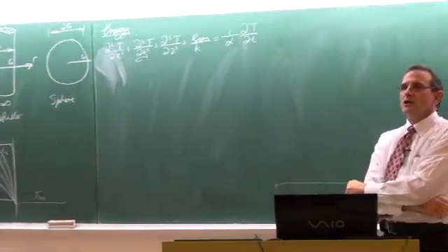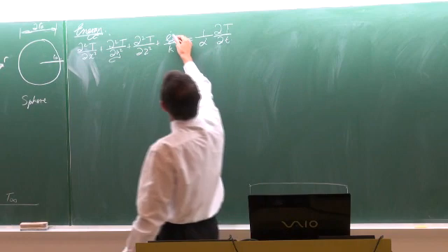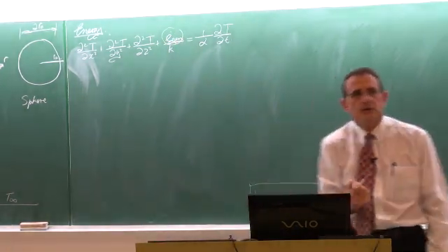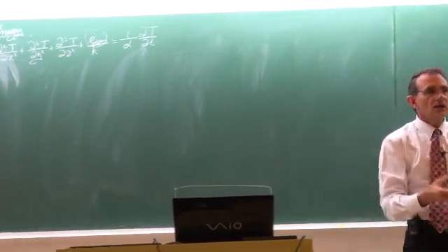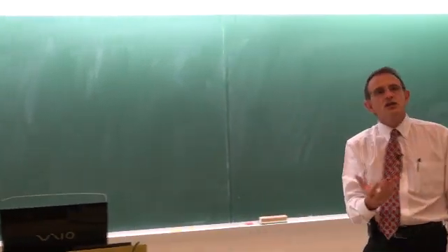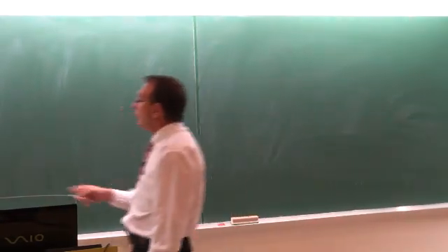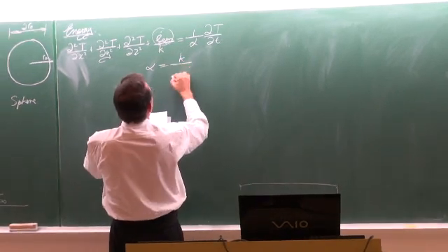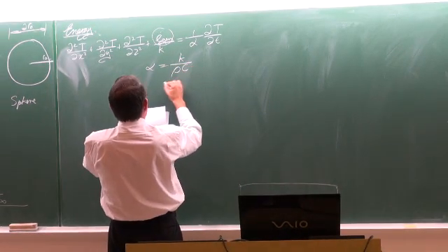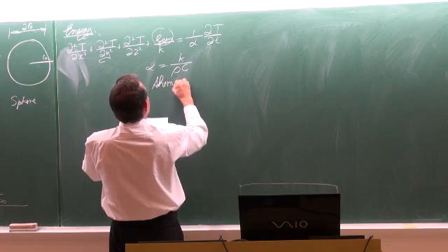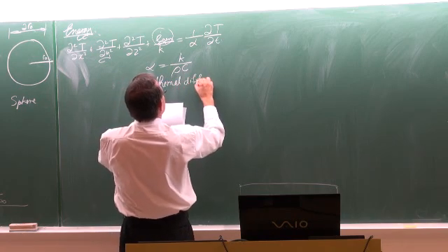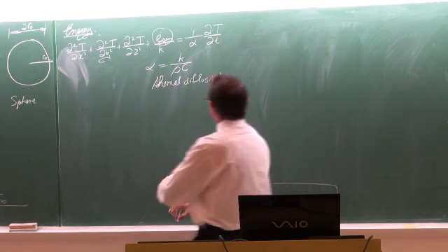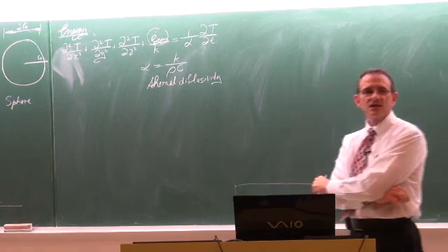What is Egen equal to? Egen is the heat being generated inside the control volume, which can be from electricity, a nuclear reaction, chemical reaction, anything like that. Alpha is equal to k divided by rho C, and that is called the thermal diffusivity. That is the energy equation.